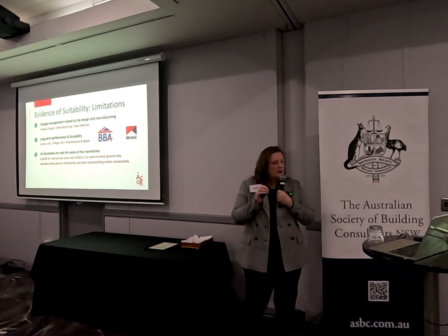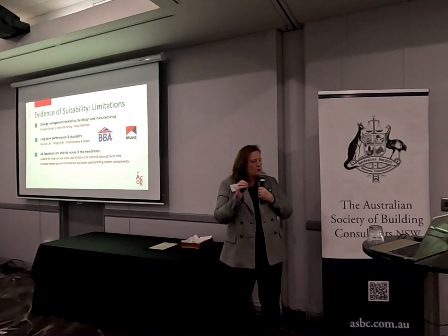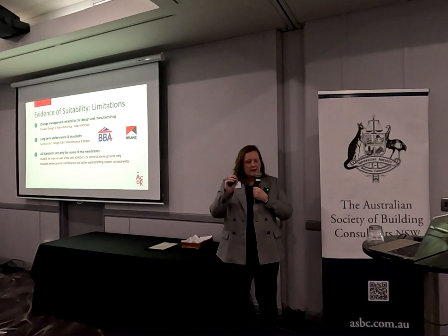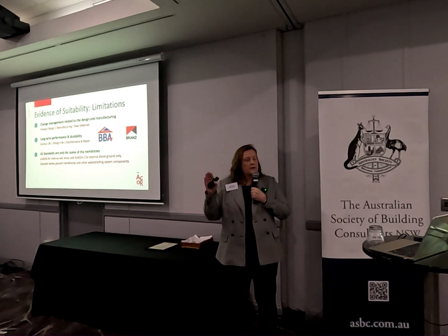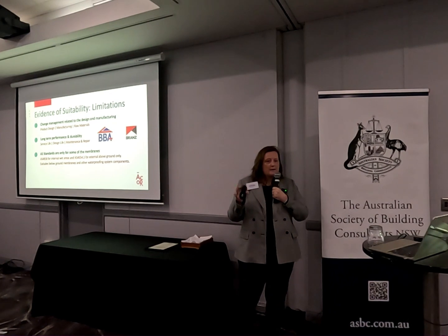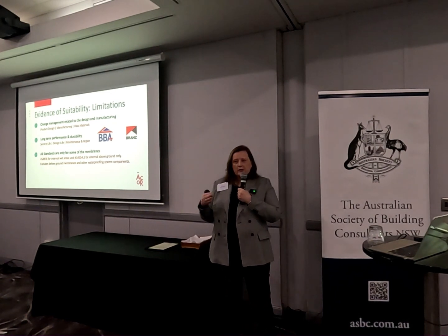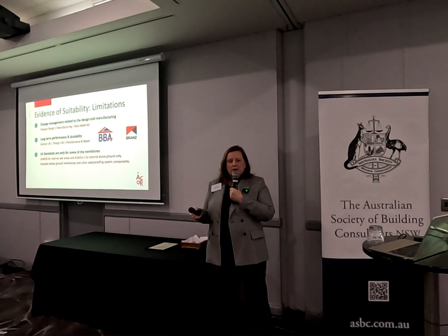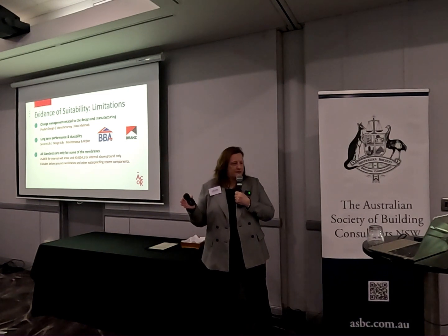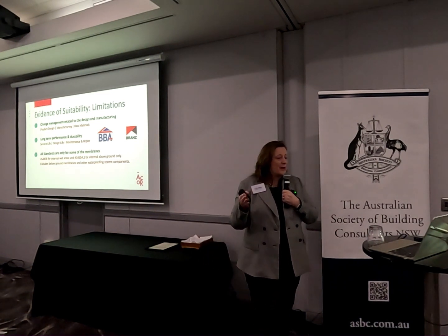Long-term performance and durability. There is a reference, I think, in AS 4654 Part 1 where it talks about suitability for service life, but that's it. That's it in the whole standard. It doesn't really explain what that means or how that's measured. Sorry, that's in 4654 Part 2. So we don't really consider the service life, the design life. We don't talk about maintenance and repair. So all these things are not captured in this data, and really they are important for the long term, what we expect, what our clients expect.